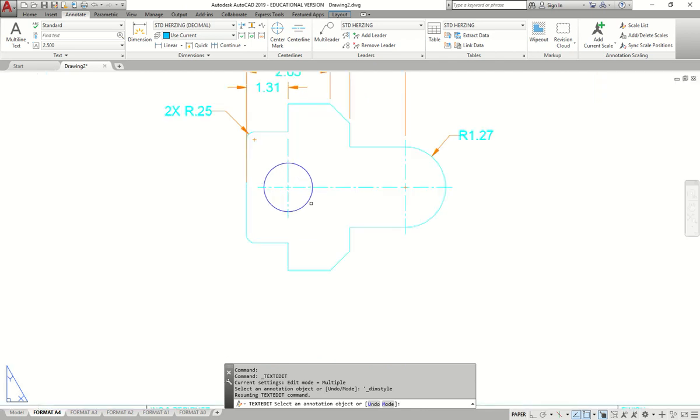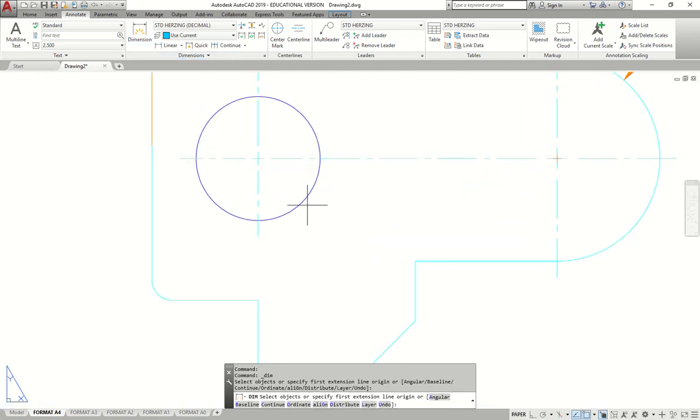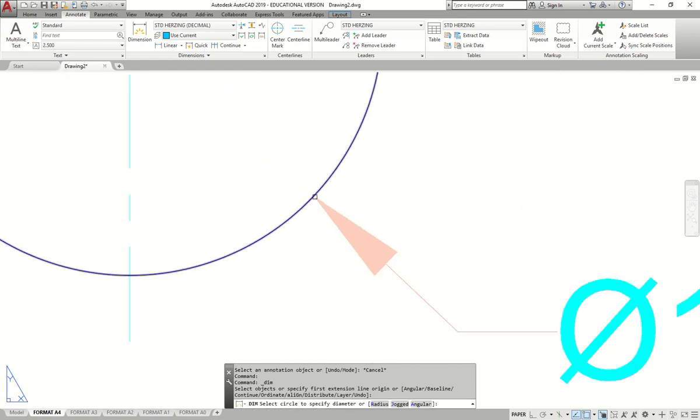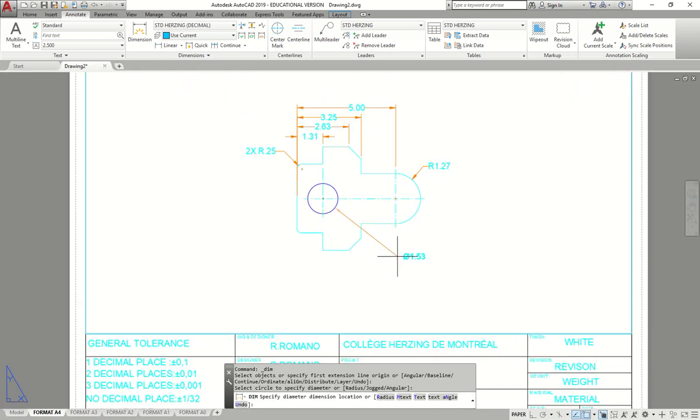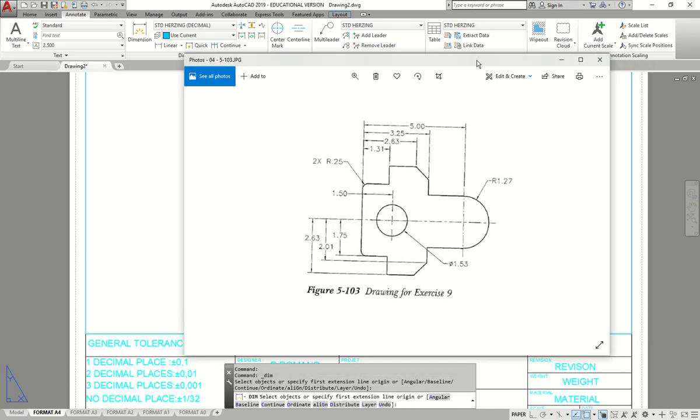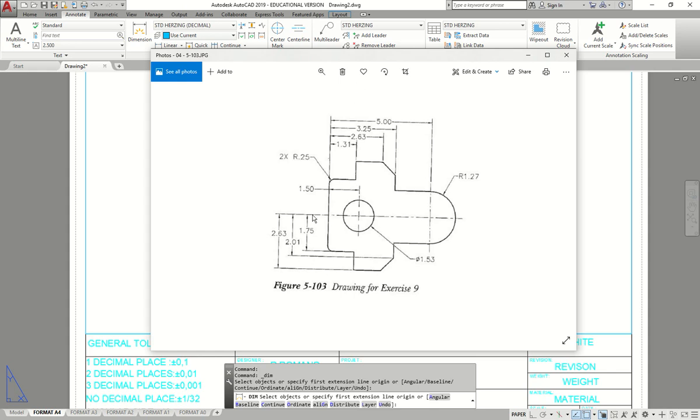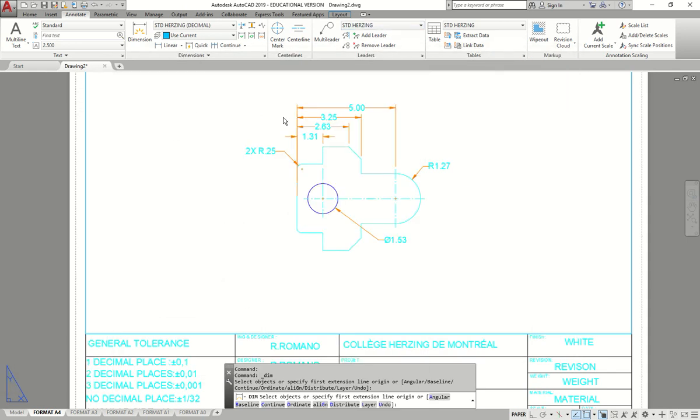Let's go now add the dimension for the diameter over here. Dimension. Again, don't just click, wait till it goes like so, and you could pull it out. We have our right dimension here. And then you guys understand you could add the rest of the dimensions for the other. So we're just missing, okay, I'll add them in. We're missing 4 more dimensions. Let's just place them in.